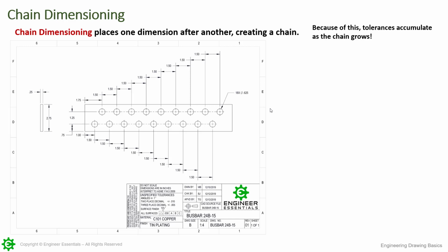Look at the drawing itself. Now we have 18 holes here, and they're 5/8 in diameter. We would have to assume at this point, based off this drawing, that this will not be a 5/8 bolt going through here, because our maximum material condition for the size of the hole would be .615. And we know that by looking down here, we've got a 2-place decimal, or that's a 3-place. So actually this would be .620.